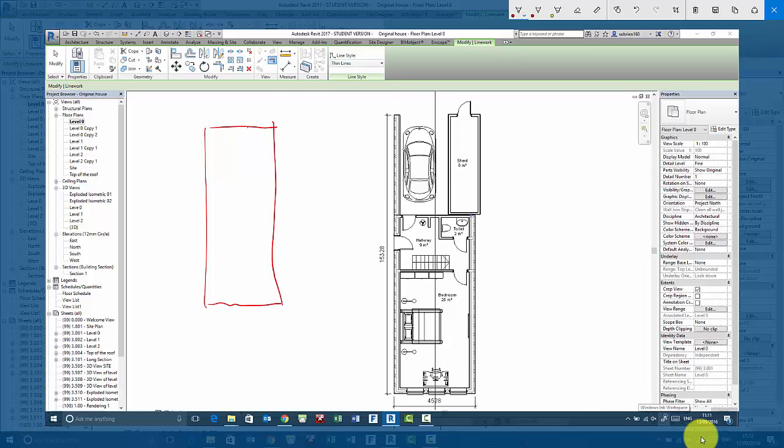It's just internal walls, furniture, kitchen, stuff like that, but no structural elements at all. So that might be one model. Then you could link that into another model that is purely concrete wall. Let's say you're making your house out of concrete. It might just be the main concrete walls, whatever your windows are like, but with no external leaf.